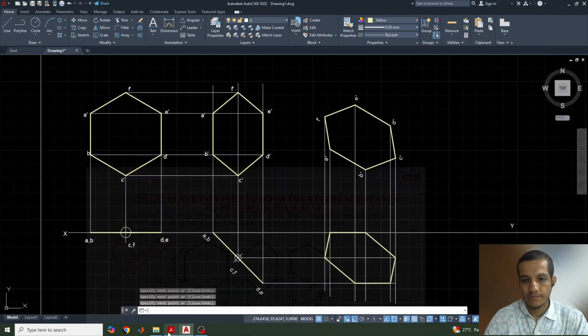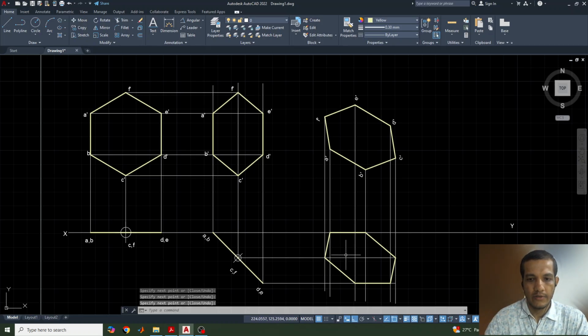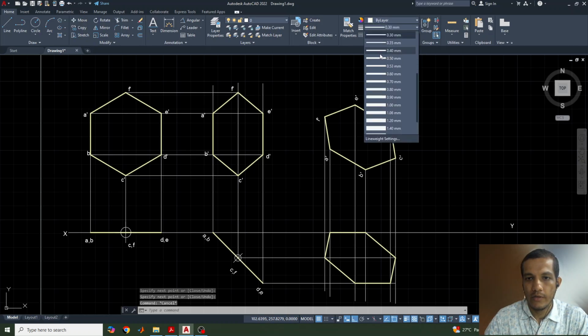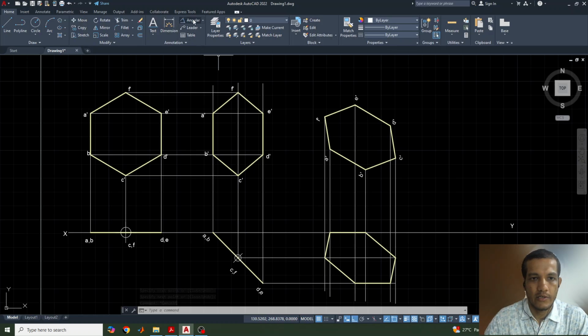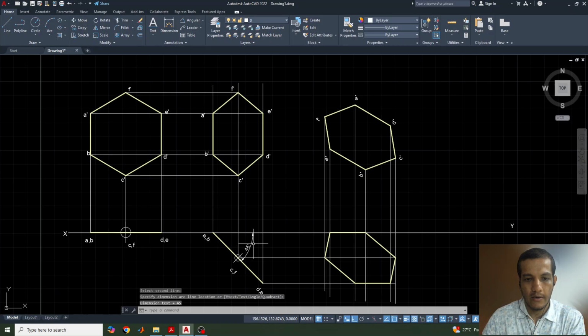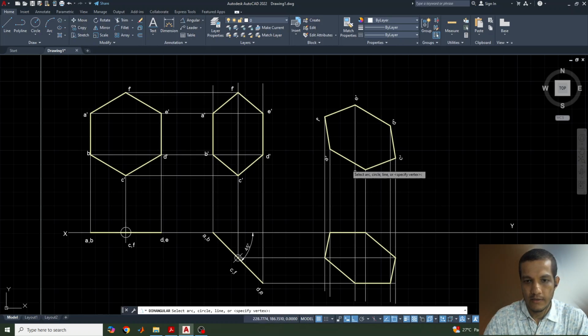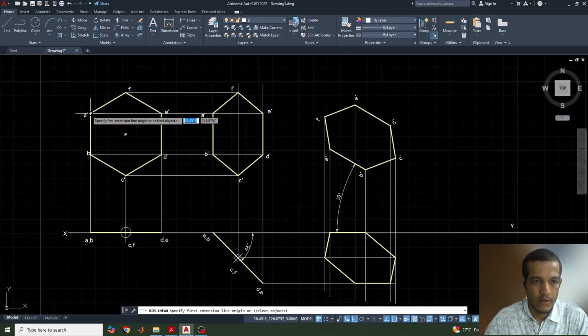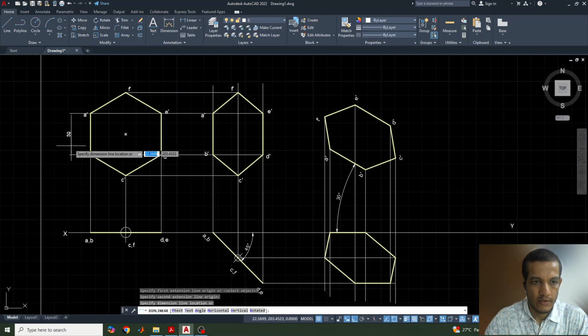Now you can see. Okay, now we need to give the namings of each of the points, and meanwhile we need to complete the dimensions also. Dimensions also you can check, angular dimension here, the angle of this reference line and this one, how much, 45 degree angle is there, and similarly this angle also 30 degree. I can select this, and this is the reference 30 degree, and similarly we will go for this other dimension, linear dimension here. What is the line edge, 30.